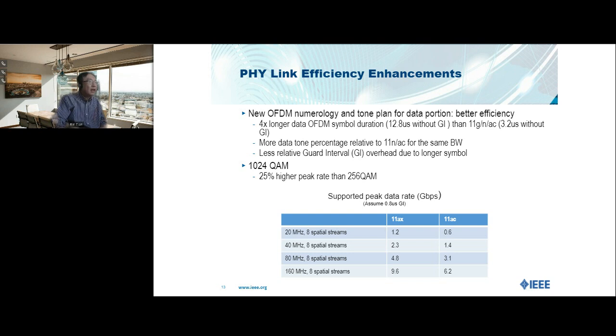We also have less relative guard interval overhead due to the longer symbol. Because we all know the guard interval is determined by the delay spread of the system, for the same environment the guard interval will not change. But because we have a longer symbol duration, the relative guard overhead will drop.